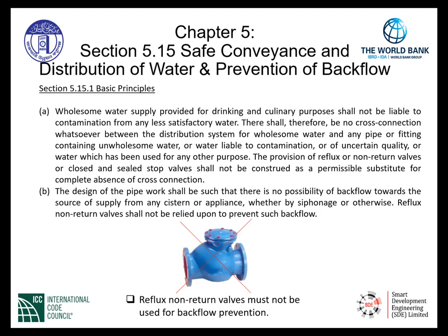The provision of reflux or non-return valves or closed and sealed stop valves shall not be construed as a permissible substitute for complete absence of cross connection. Now, the indication here does not permit the use of reflux or non-return valves to complete any type of cross-connection method. It is not permitted.